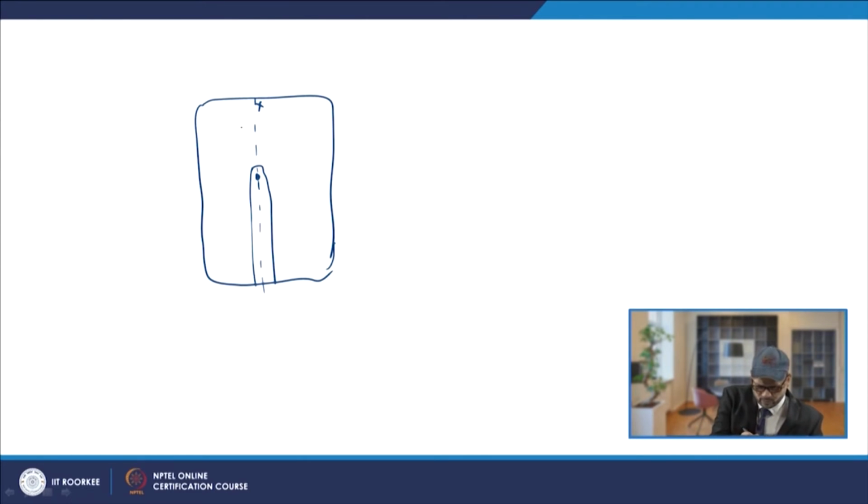Suppose you talk about this zone, that is your AA. In the melted zone, just after it has been melted and your torch is here, if you talk about the change in temperature and the longitudinal stress value, just ahead of this you have delta T as 0.